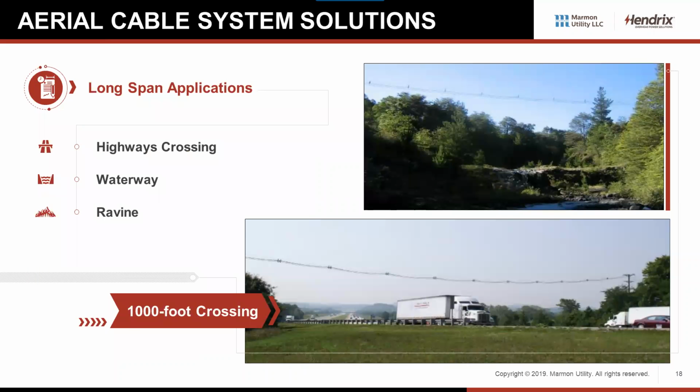Long spans are another common application. And the nice thing about spacer cable is that, typically with bare wire construction, you really have to size the conductor for the tension and the span that you need, especially if you're doing a highway crossing or a river crossing or something like that. Like I said, all we're concerned with when it comes to span length is the size of the messenger.